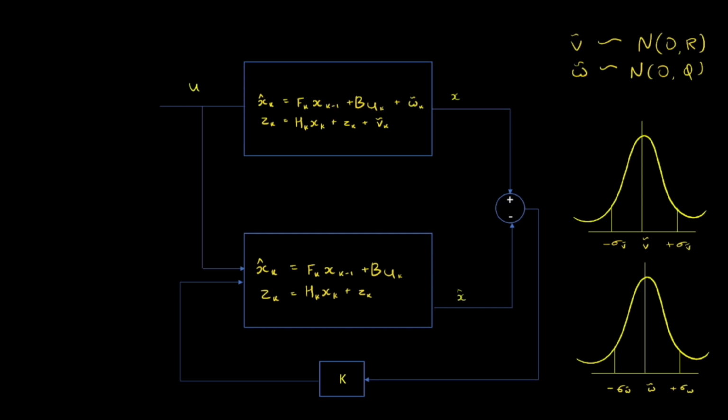It would be different for an IMU, it would be different for GPS. Whatever sensors we are using, we have to do ground-level research on what noise they have, and we tweak those Q and R accordingly.